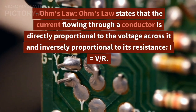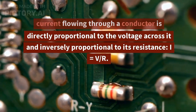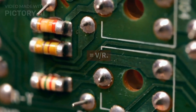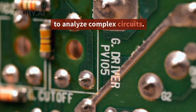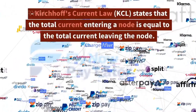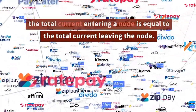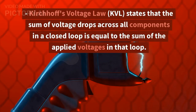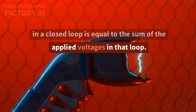Ohm's law. Ohm's law states that the current flowing through a conductor is directly proportional to the voltage across it and inversely proportional to its resistance. Kirchhoff's laws. Kirchhoff's laws are used to analyze complex circuits. Kirchhoff's current law states that the total current entering a node is equal to the total current leaving the node. Kirchhoff's voltage law states that the sum of voltage drops across all components in a closed loop is equal to the sum of the applied voltages in that loop.